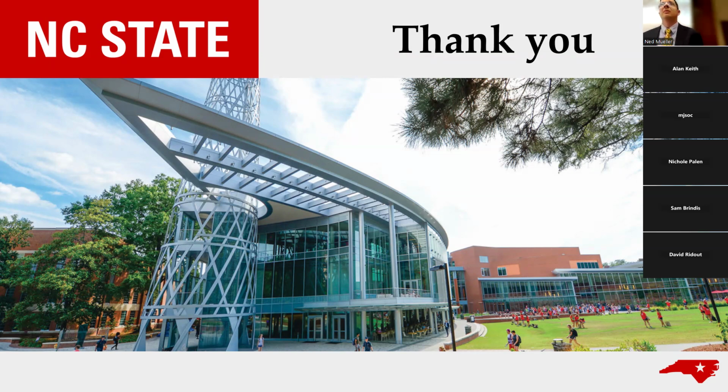Issue with hydroplaning, do you have anything like that? Is that considered when you come up with a quarter inch of allowable rutting? Yeah, it's baked into that. The DOT has just recently created, with the help of a consultant, what they call a hydroplaning assessment tool, which allows them to more objectively determine the likelihood of that rutting.